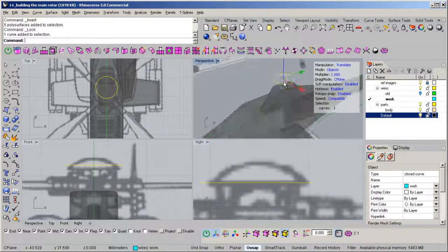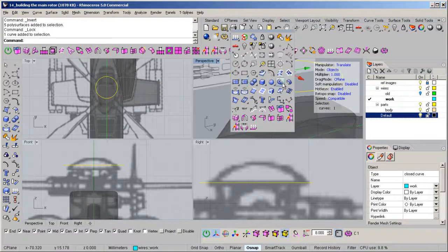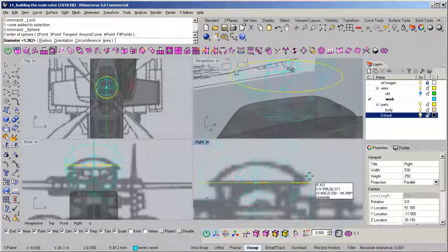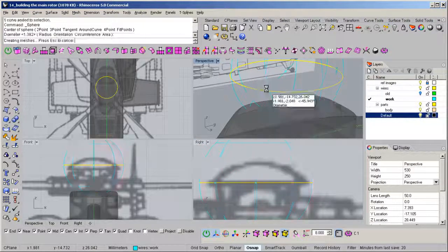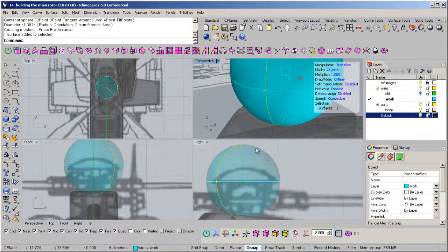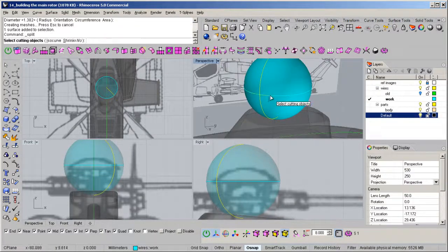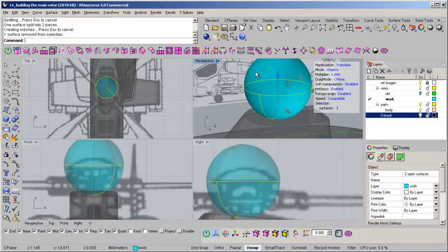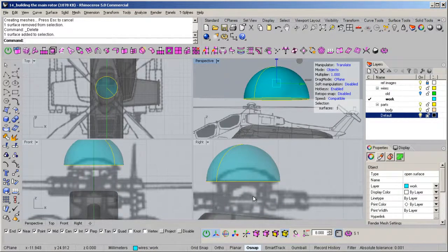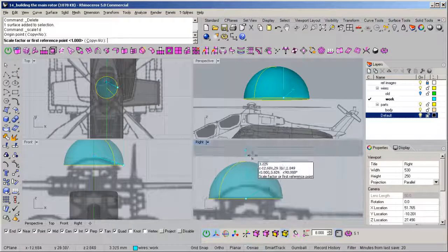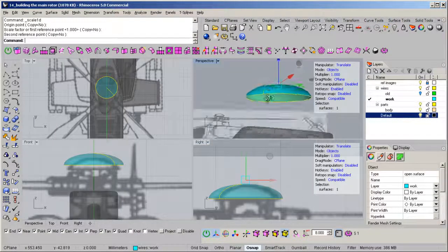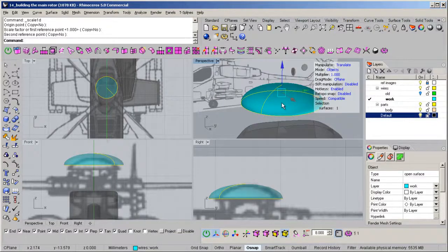All right. From here, we can draw a sphere from 0 and just pull it to that edge, just like this. Select the sphere. Let's do a split with that circle cutter and delete the bottom. Go to 1D scale and just pull it down. When you're finished, let's cap it.